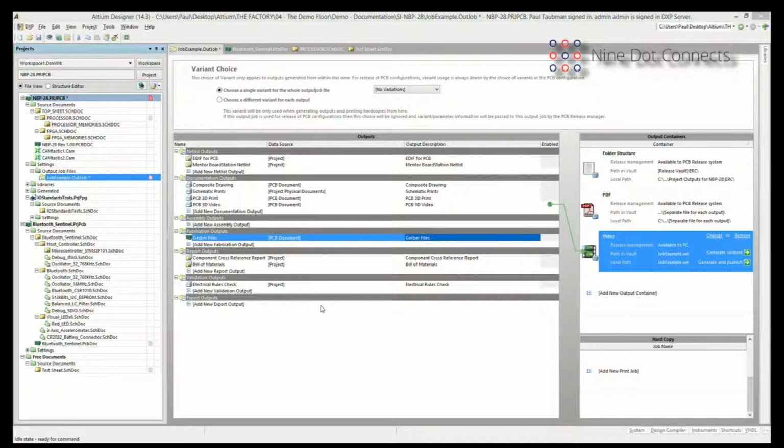so that you don't have to keep going into the file menu of PCB and have to say, well, create the Gerbers, create the bill of materials, create the ODB++, whatever you have to create. You don't have to keep going in there and separately running these things. Because number one, you're going to forget to do something. And number two, if you have to change something, you're going to have to go through that process again. And that's just a lot of administrative work for what you need to do to get things done. And Altium can do all of that in one file for you.